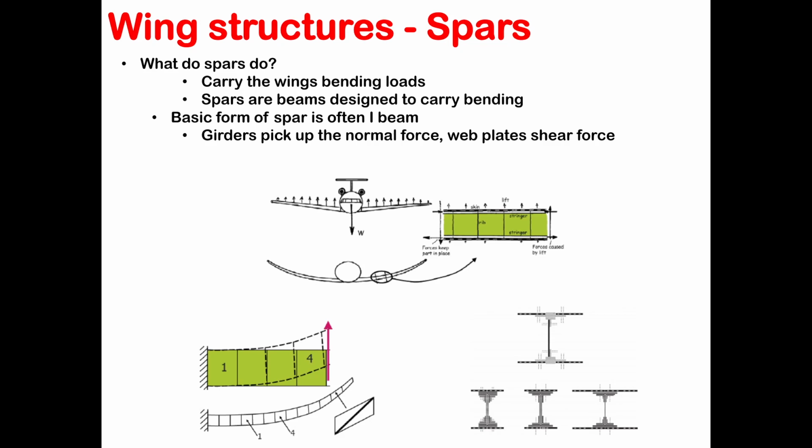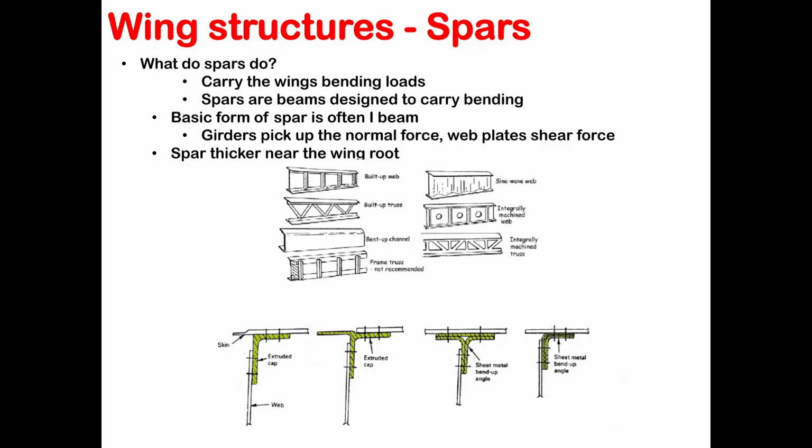I mean, the deflection, the distribution of the force, essentially. So the equilibrium between the normal forces in both girders and the spars near the wingtip and the upward bending moment will result in a relatively small force in the wing root, right? Okay. So you always get into the manufacturing problem because you need to have a thicker spar near the wing roots.